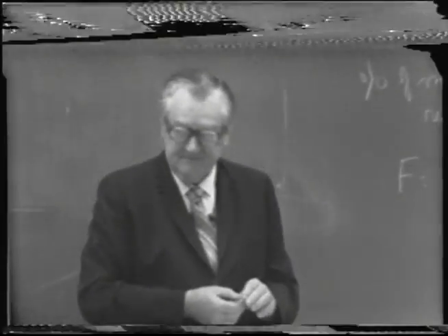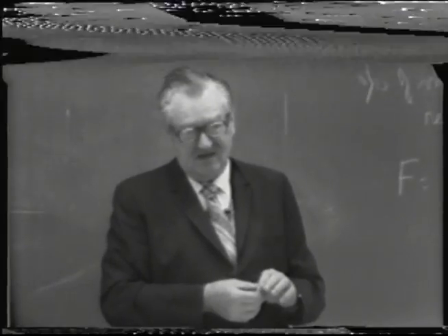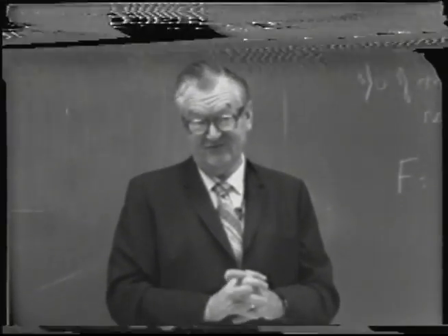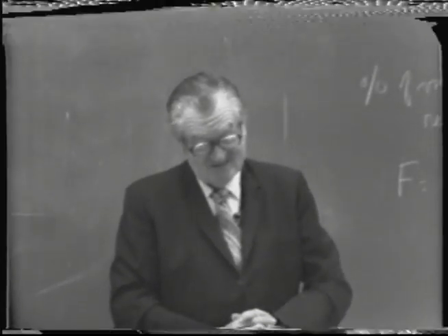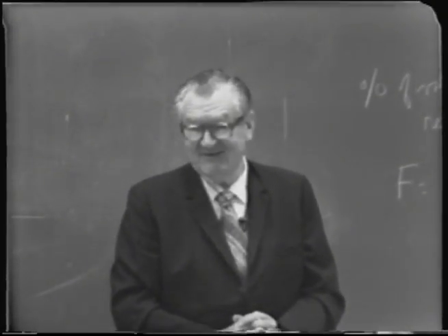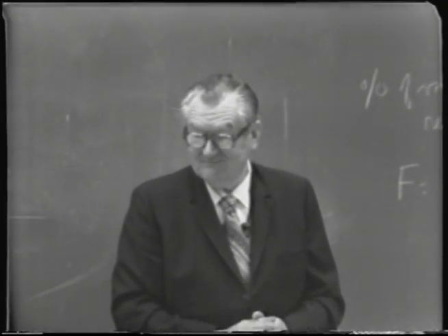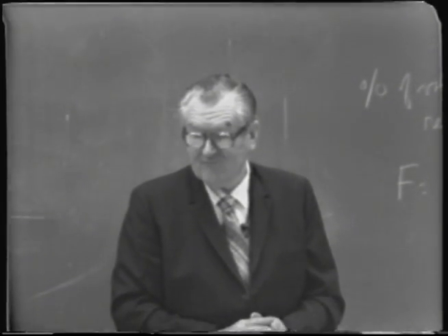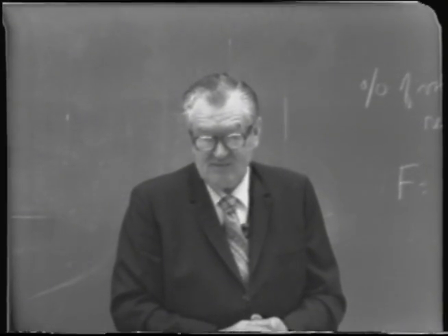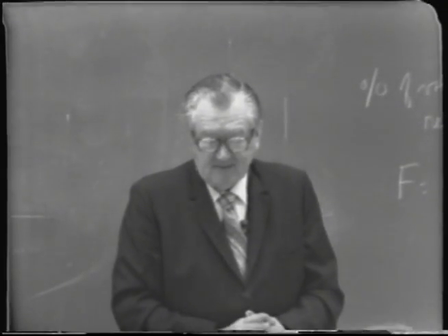What does the height depend upon now? Well, the height depends upon, of course, the number of trays. In other words, if you have to have 50 trays, it's going to be essentially 5 times as much as if you only had 10 trays, everything else being equal. Is there some relationship between how far apart the trays are and the increasing diameter of the base?